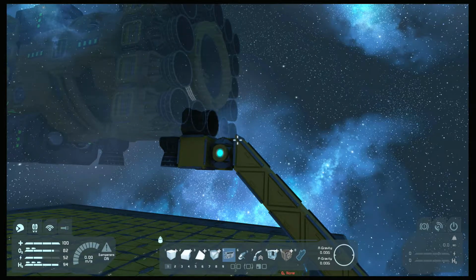So what I want to do when I use a projector, when I take whatever blueprint that I want to do something like this, is have something I can grind down that's not critical, that's not part of the original ship, and certainly not my projector, so I can free up the ship. It's a grindable piece that I can get rid of that will then disconnect what I'm trying to weld up from this stationary projector.